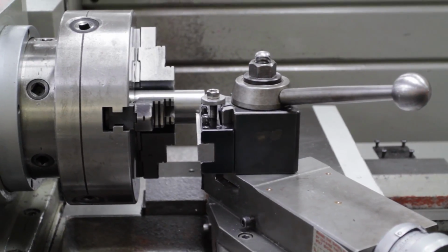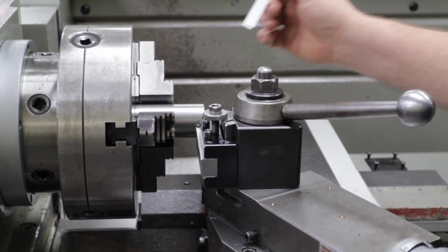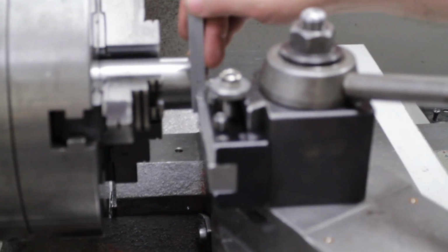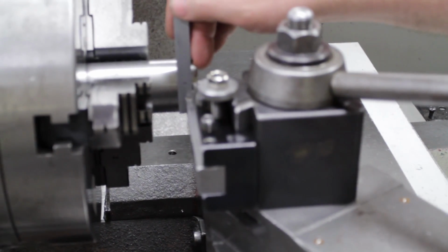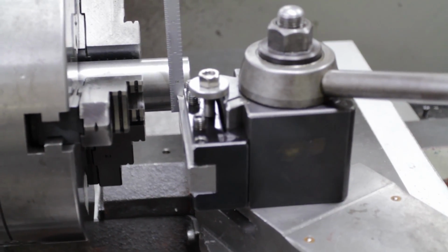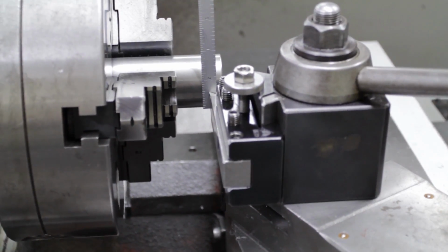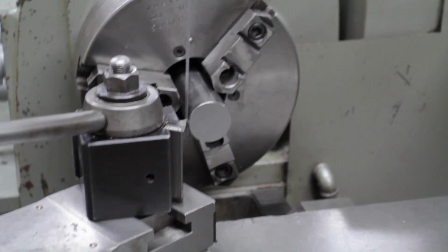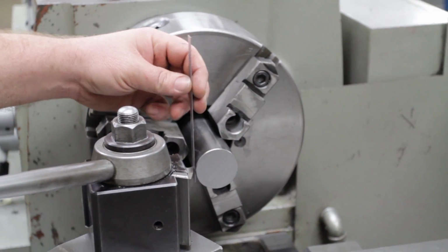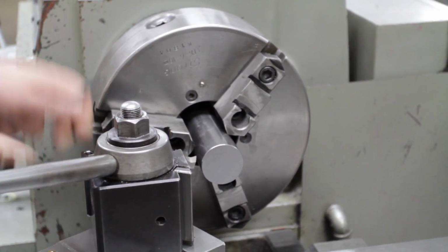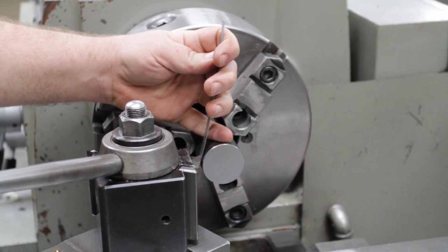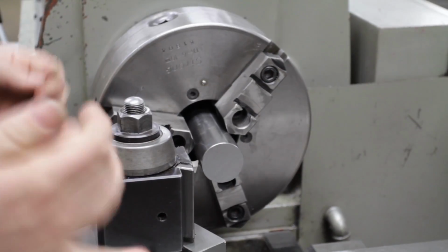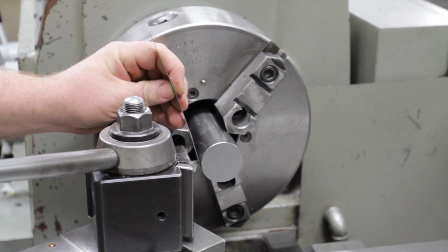And as I bring it up to the workpiece, you want to use your machinist scale or your 6-inch rule and just pinch it in between there. When you pinch it in between there, you'll be able to stand on the end of the machine. When you're standing on the end of the machine, what you want to check is to see if that ruler is straight up and down. If your tool bit is too high, you will see the ruler leans away from the operator. If your tool bit was too low, it would actually lean towards you.